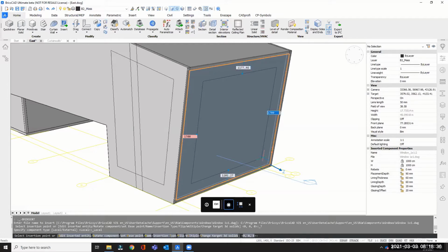So just remember to tab and make sure also that you are in the right dimension or direction of this placement. This is something that we also get asked a lot about. And if you see on the lower part, there's also, again, the hotkey assistant, which we also have been discussing all throughout the sessions previously and also yesterday.